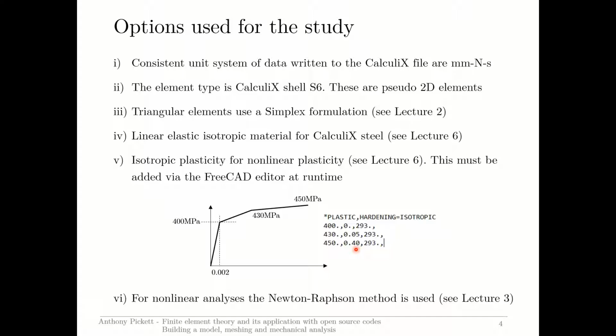The nonlinearity comes from the elasticity, or the elasto-plastic matrix for the material as it plastifies, and the stresses are no longer linearly related to the strains, and we have an iterative solution necessary to find the stress state that stays on the von Mises yield curve for any given displacements or strains.